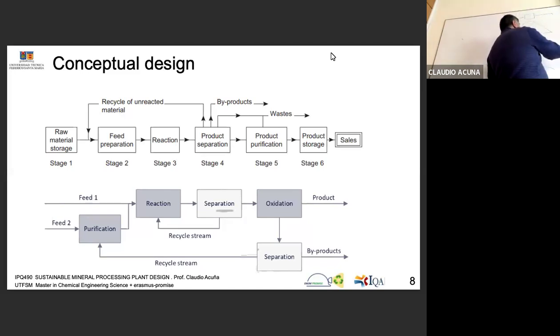In this case, you feed here, you have a product here, it goes to the cyclone, overflow goes out, and then you return here. This is direct grinding. Put the material in the ball mill, reduce size, and then what is over the size goes as an underflow and recirculates.